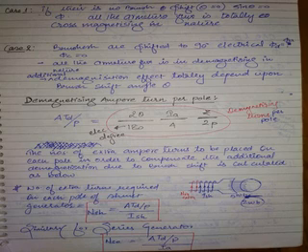Now the concept is, let us consider, we will split this. This simply, you can split this in order to write the expression, demagnetizing ampere turns per pole, individually write. What is demagnetizing area in the entire armature? Since you are making per pole basis, let it be 180 degrees. Because you are telling per pole, how many electrical degrees? 180. Next. In this total 180 degrees electrical, how many electrical degrees is the brush shift problematic area? 2 theta. This is demagnetizing region.